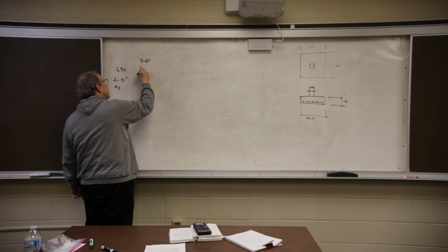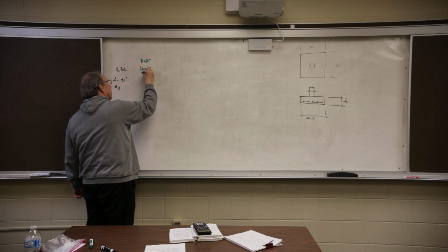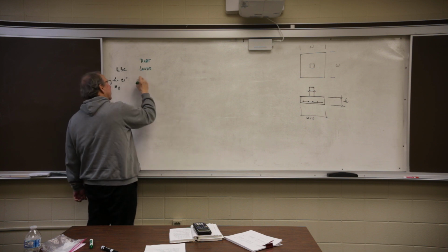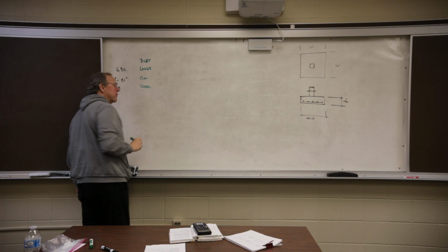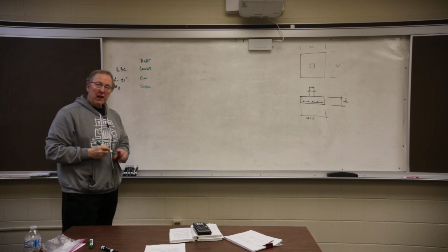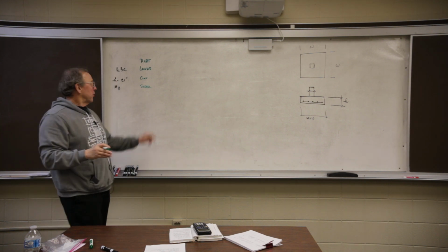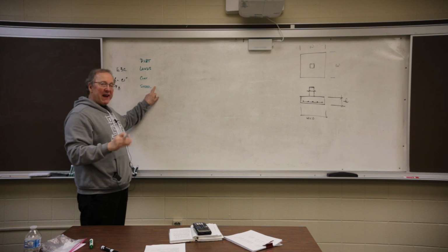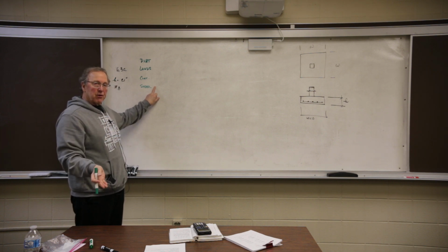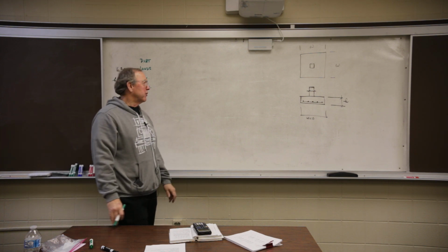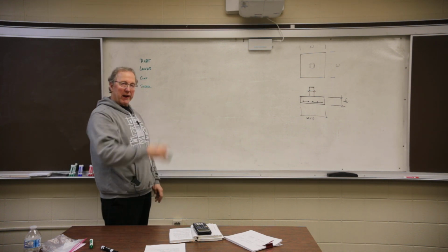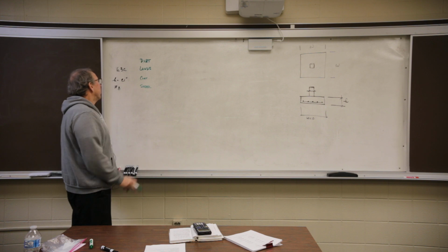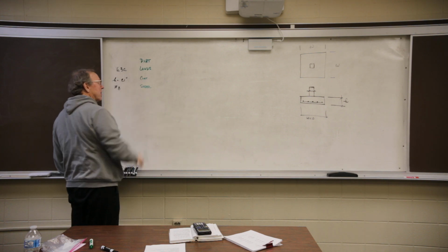You're going to have loads, just like before. You're going to have concrete and steel. Now, steel is going to be abbreviated because with a wall footer, we found the main steel and the longitudinal. Here, all we got to worry about is one bar, the main, and it's repeated at a 90-degree angle going the other direction. So, there's our categories.